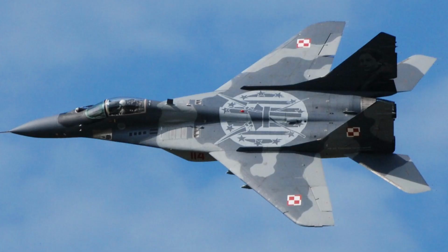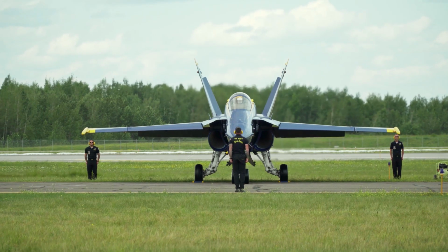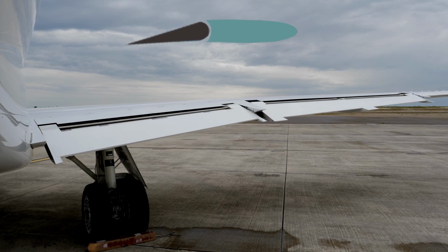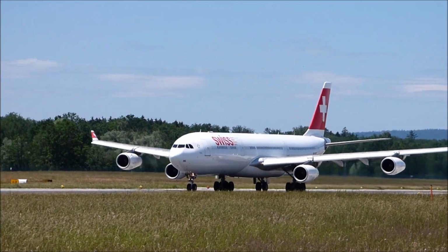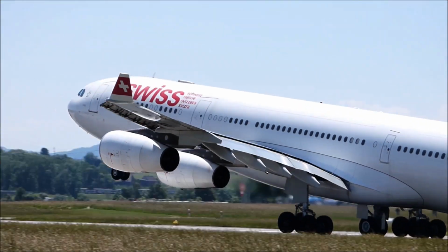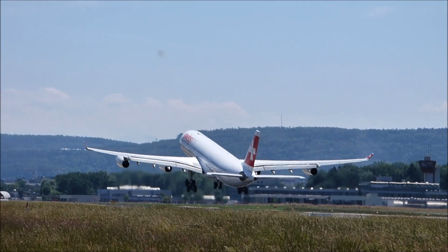This is the flap, situated at the trailing edge of the wing, on the inner side. Both the flaps operate together in the same direction. It can produce lift as well as drag, depending upon at what angle it is set. At the time of takeoff, it comes down at an angle between 15 to 25 degrees. Its deflection angle varies from aircraft to aircraft. When the flap comes down during takeoff, it increases the surface area and also changes the shape of the wing, helping to produce more lift. So with lesser speed, the aircraft can take off and also requires a shorter runway.